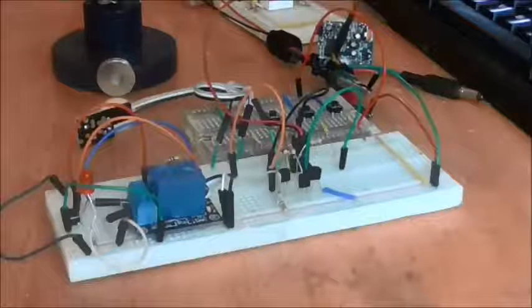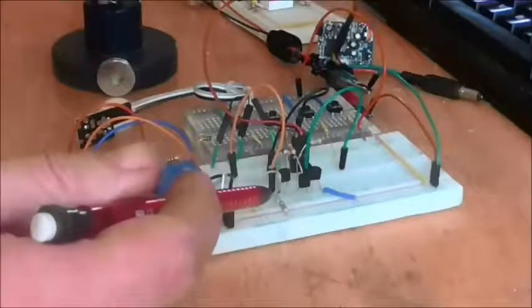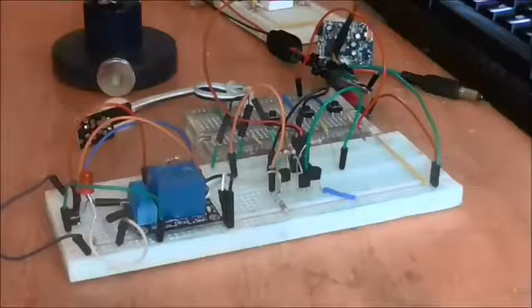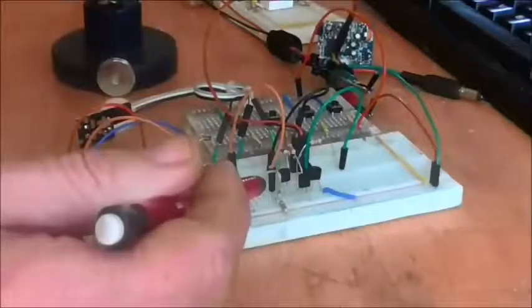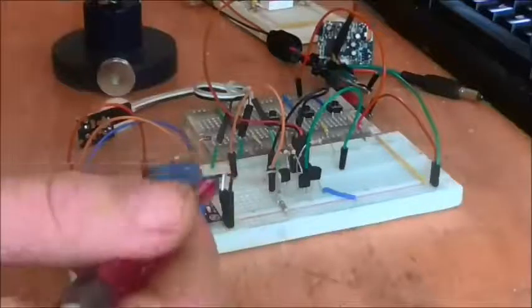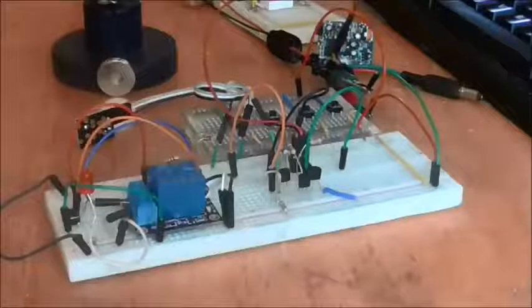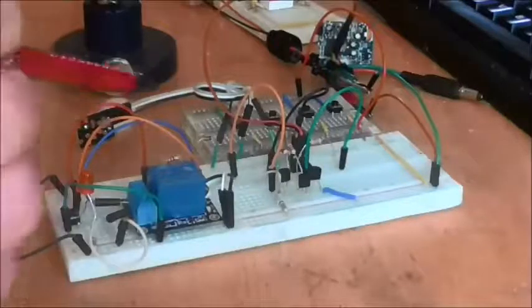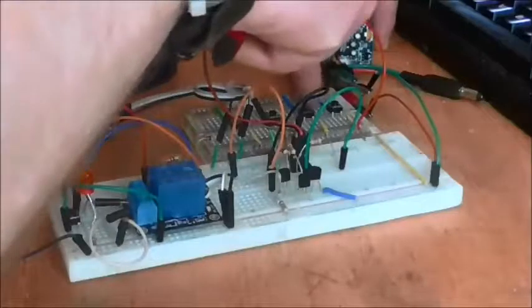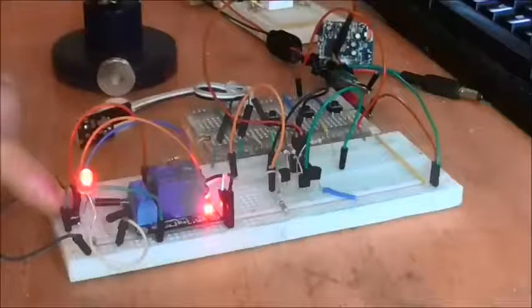You might have heard me mention earlier the problems of fan out, and what I was finding was that as I put the thyristor here at the end of the gate, what we were getting was a problem with sending the signal to the gate of the thyristor and sending a signal from the thyristor to a transistor to drive the relay. So what I've actually ended up doing is latching the relay electrically by its own output. And if we look at that in action, there we are, and by doing that I can also put in a reset switch.